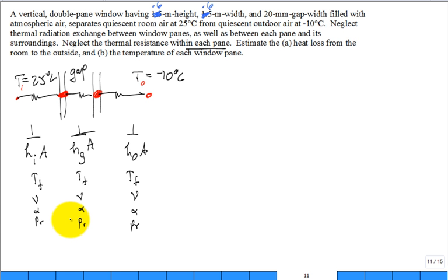It's back to my analogy with the merry-go-round. You just have to jump in there somehow, in one shape or form. So what I would do is assume some of the pane temperatures, calculate the film temperatures, get the fluid properties, use the correlations, get the H's, solve for the updated temperatures, and if I feel like it or I have time, update the estimate of the film temperatures.